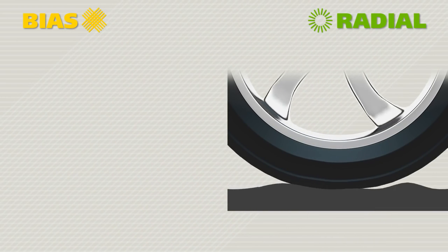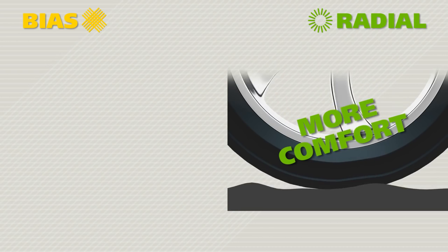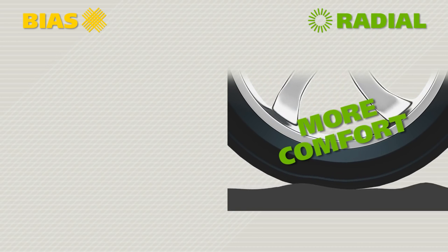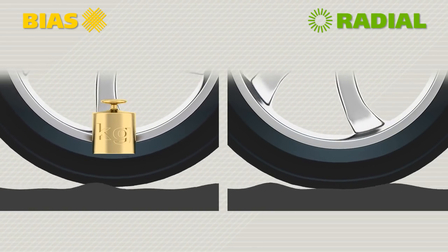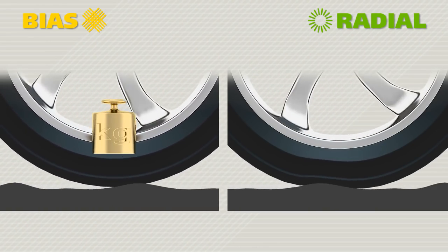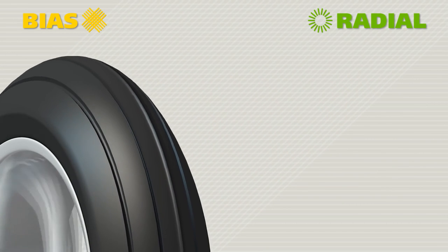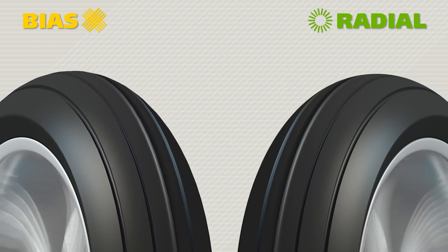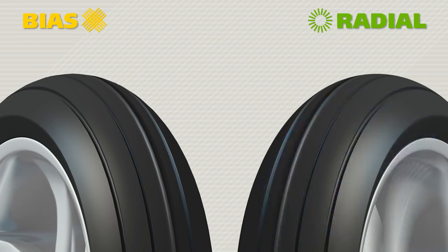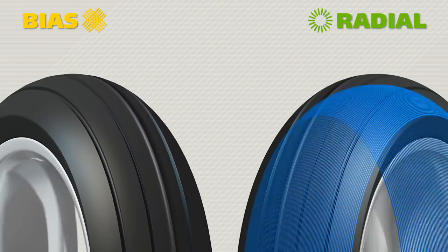Thanks once again to its flexible sidewalls, a radial tyre offers greater ride comfort at high speed by cushioning irregularities in the road surface. A bias tyre, however, is better able to withstand a heavy load as its sidewalls are more rigid. At high speed, the profile of a bias tyre becomes deformed to the extent that it affects handling. A radial tyre, however, remains stable thanks to its crown belt with a continuous integrated cable around the circumference.